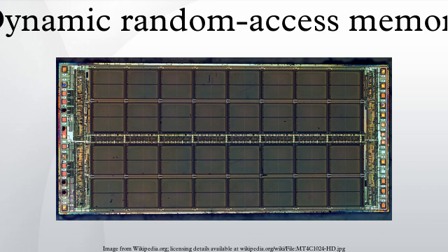refreshed. Most DRAM chips include that counter. Older types require external refresh logic to hold the counter. Under some conditions, most of the data in DRAM can be recovered even if the DRAM has not been refreshed for several minutes. Memory timing. Many parameters are required to fully describe the timing of DRAM operation.